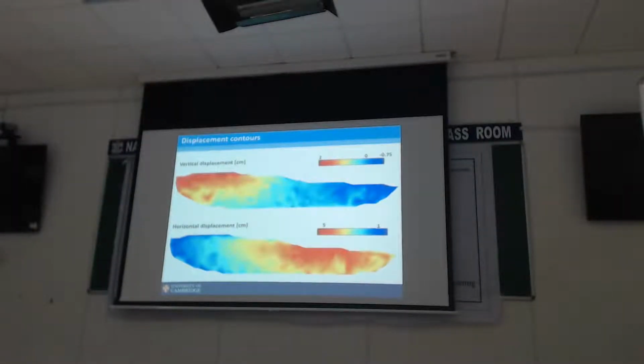And you can separate out the vertical and horizontal components of these and use nice MATLAB contour plots to show which bit is going down. Obviously, upslope is going down, and this bit is going up. Horizontally, that bit is moving most, this one by less compared to this bit. Okay, so this is all cool and neat for the ATG test. So we're looking at displacements in terms of centimeters here, so 50 millimeters or so, right, at prototype.